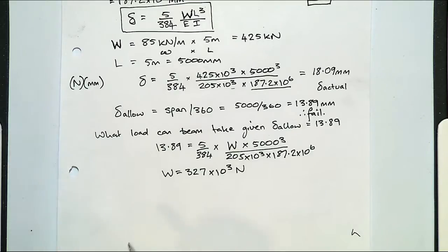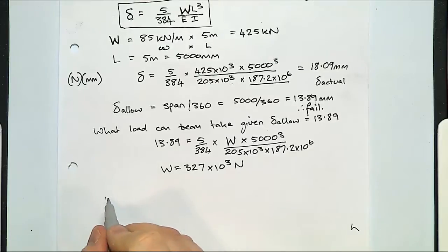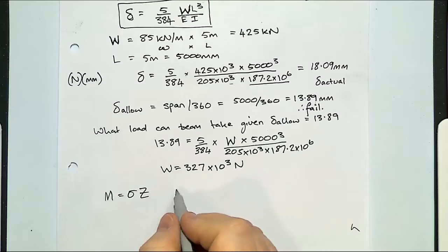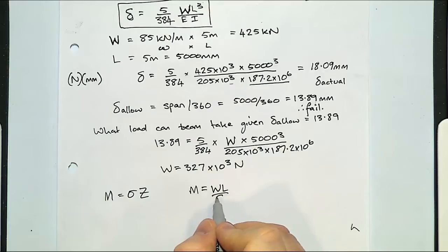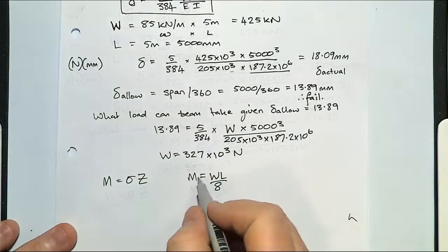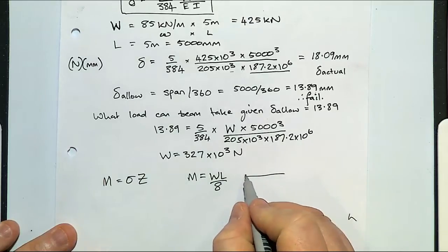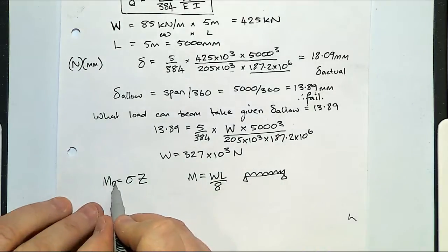And we also introduced the strength of the materials. From our theory of simple bending, we had these formulas where you could have M is WL over 8, which is looking at the moment that's been applied due to this UDL. That's your moment of resistance of the beam.